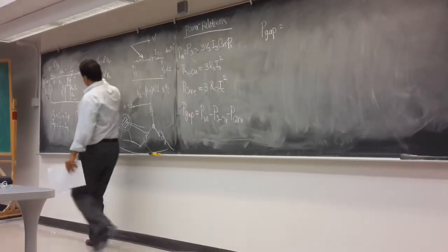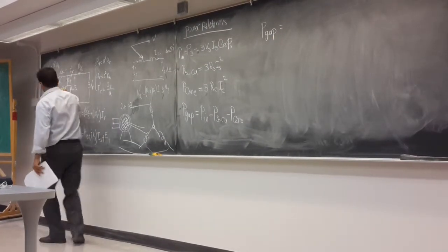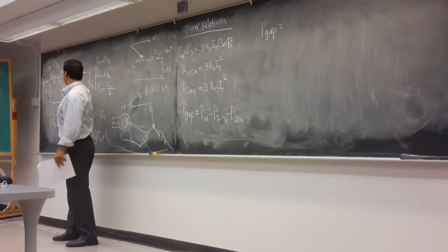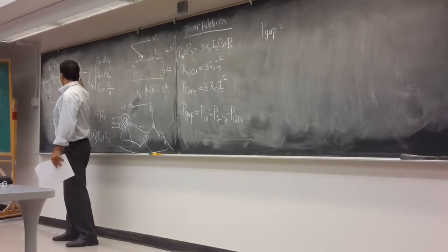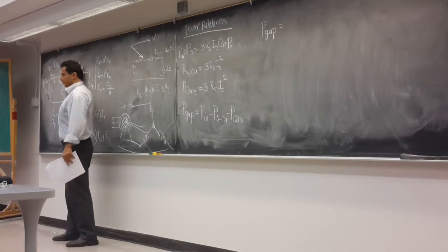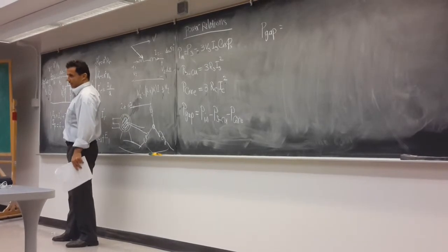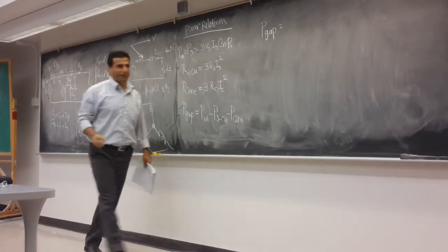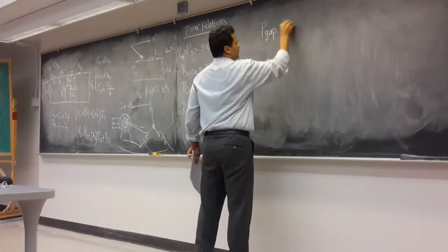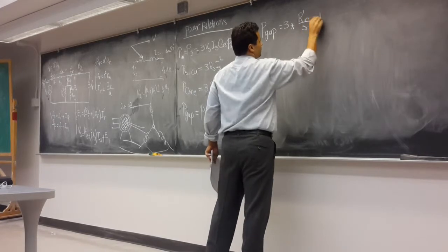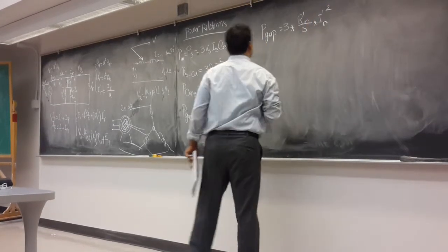This is this part, right? This is the gap. Here was the stator. We went to the rotor, right? The power going through here is going to be 3 times this resistor and this current to the power of 2, right? Because this one doesn't dissipate any active power. This is an X, right? So P gap is 3 times